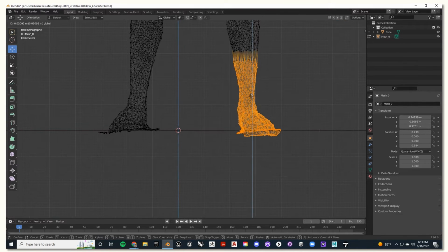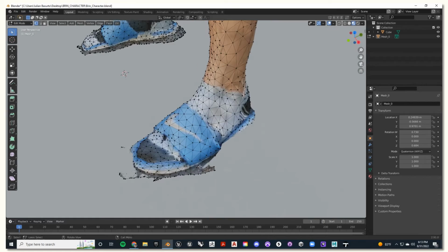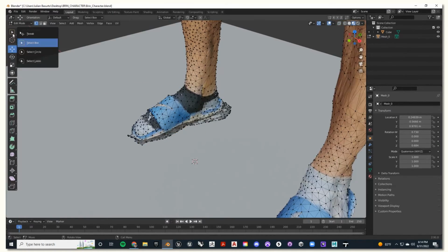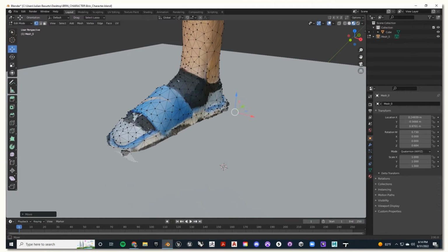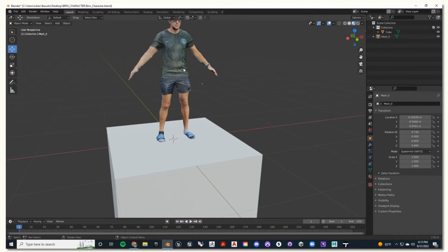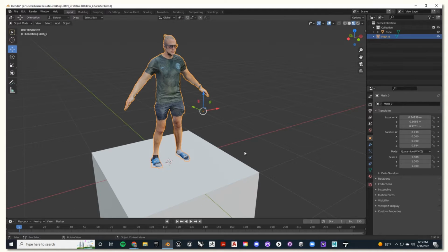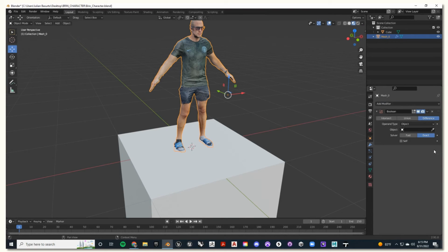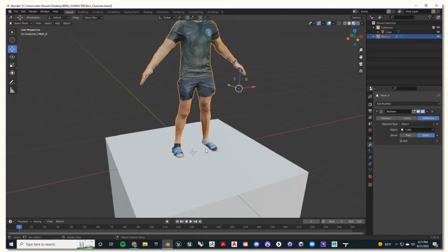Now I'm going to go through the process of cleaning up these feet by dragging any mesh and bringing it underneath the cube so that when we use the Boolean splitting command, it'll clean the feet thoroughly. Awesome. So once you've done that, select your object, go to the wrench icon on the right, select Add Modifier, Boolean Modifier. Then you can use the eyedropper tool and select your cube as your splitting object.